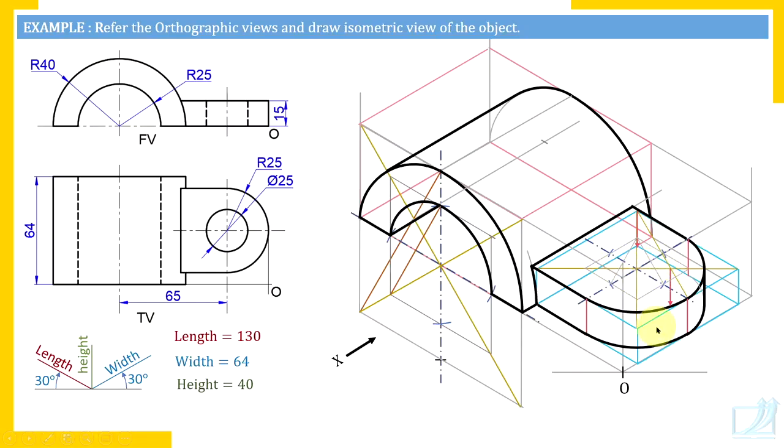Now use these 4 centers. Remember, the longer arc's center is in the opposite quadrant end of the shorter diagonal, and the smaller arc's center in the same quadrant. To draw these arcs, we never use the real center. So don't draw any arc through this real center. Check how we draw those arcs once again.